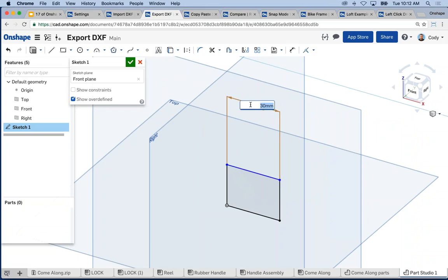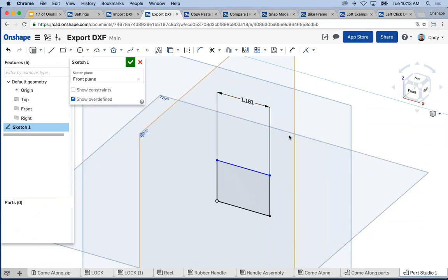And the same thing goes for inch, by the way. You can convert in a metric part to inch just by typing inch. But a key thing, another commonly asked question, if you have a part that's largely one unit style, but then maybe one or two dimensions are a different one, you can just type in that value, type in the units, and it will convert it for you. So again, you can change the units on the default level, all future documents. You can change the individual units of an individual document, or you can even enter in the units for a specific dimension and it will automatically convert it. So if you're doing a lot of mixed unit style modeling, that can be an important one.